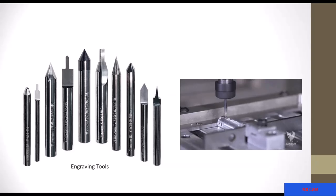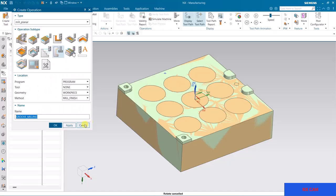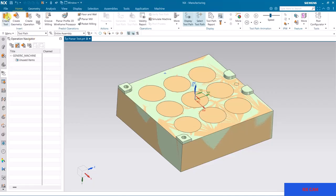And for engraving, we can use different types of tools. Mostly we use this type of tool for engraving any number, part number on the surface. This is also an engraving tool. All are engraving tools. Mostly we use this kind of tool, right? But this engraving tool is not available here, so we will create this type of tool. So before selecting this, click here and add a tool.